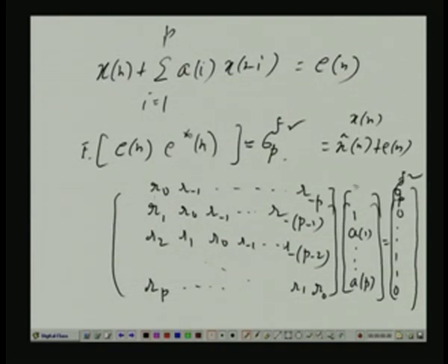Now take the first row times this column, whatever you get, that is sigma p f square. That is the input variance. So what is the output power spectral density? Input variance times, because input is white, so input variance times mod square of the transfer function.